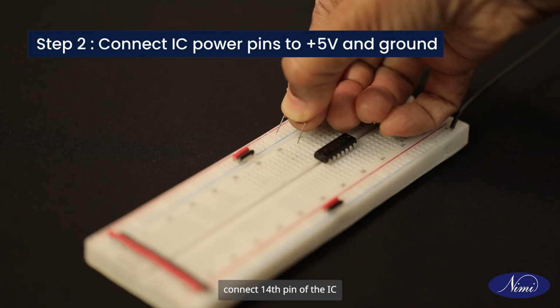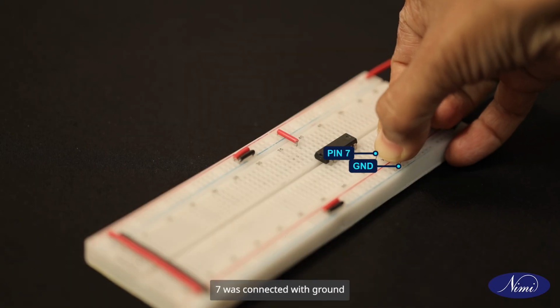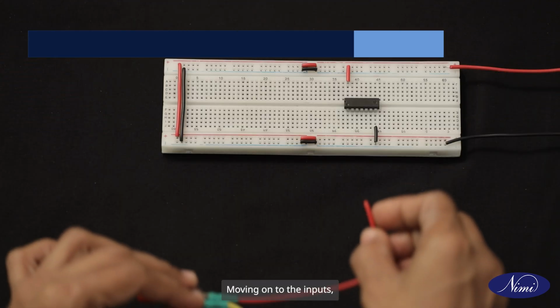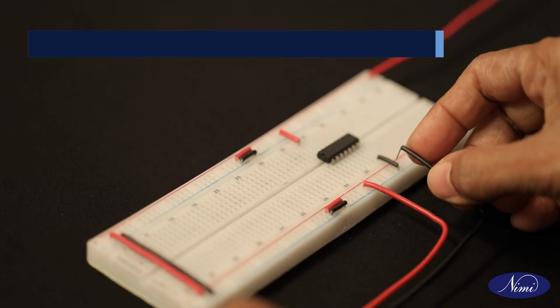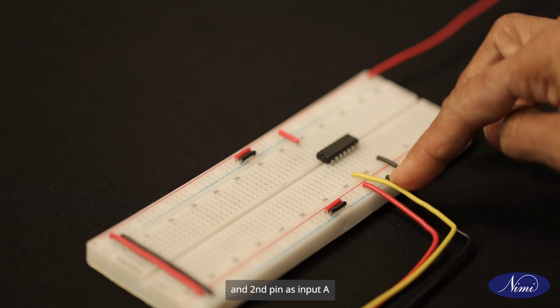Next, connect 14th pin of the IC to the plus 5-volt power supply. Then, make sure pin 7 is connected with the ground. These connections are vital for providing the necessary power and establishing a common reference for the circuit. Moving on to the inputs, connect the toggle switch to the power source and ground. And connect switch S1 to the first and second pin as input A.